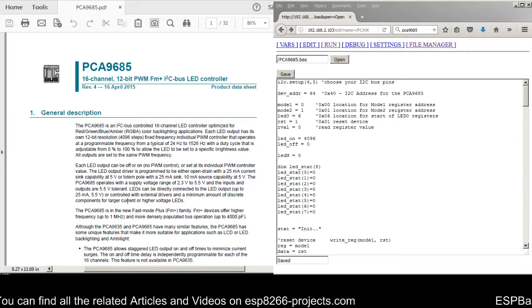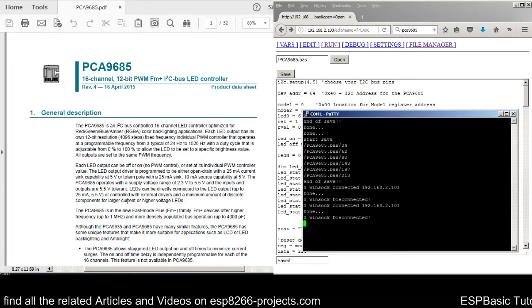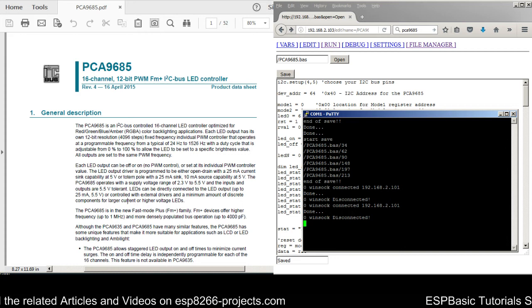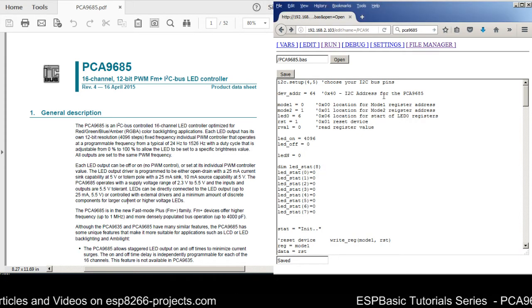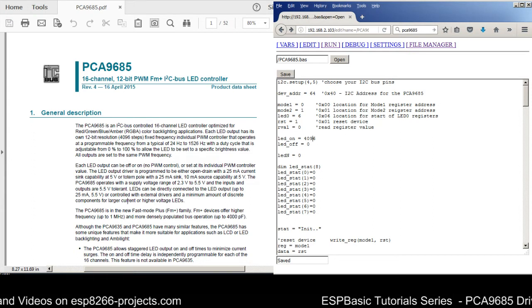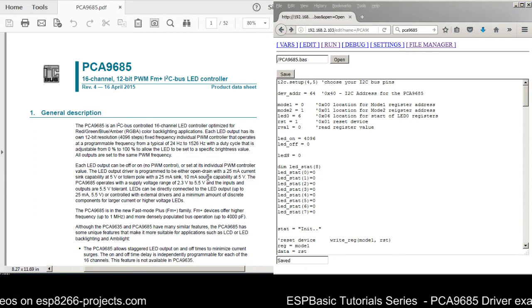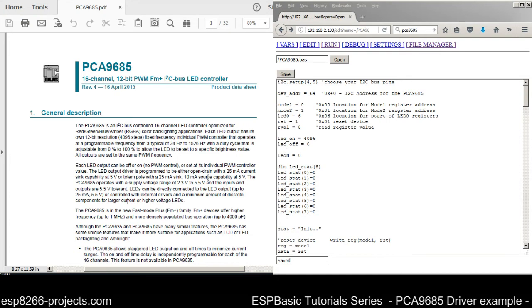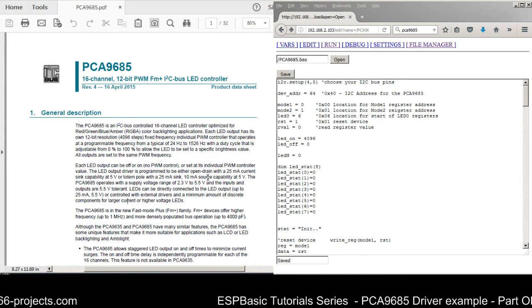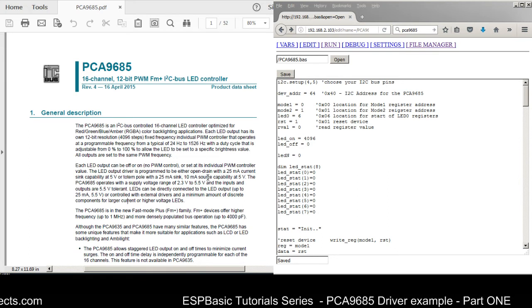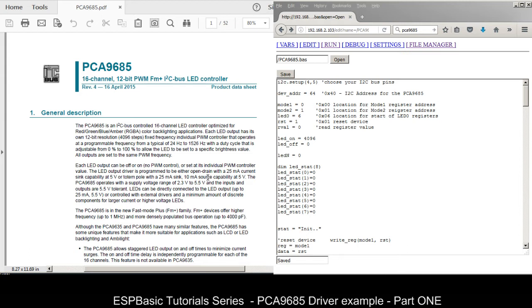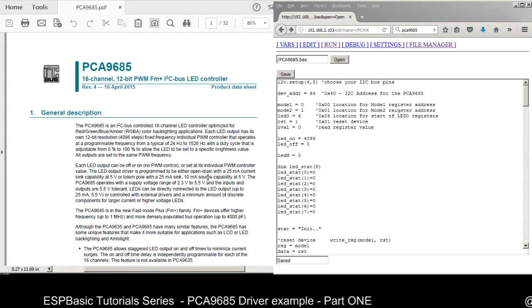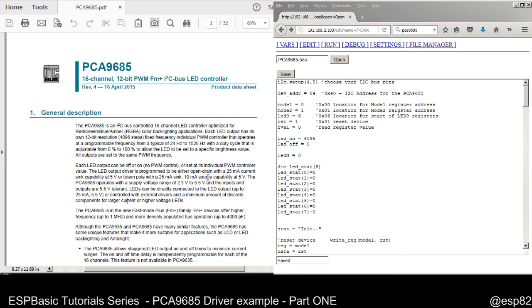I think this is a quite handy setup. Just connect on the serial port with PuTTY to see the status, open your web editor in your browser, and keep an eye on the datasheet, because without properly reading the datasheet and having it in front of your eyes, it will be very hard to write the proper values in the proper registers and make things happen as you wish.